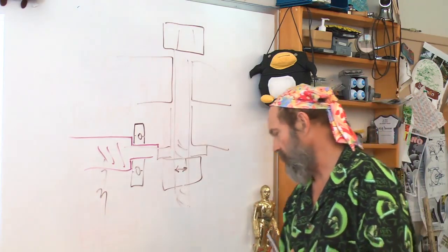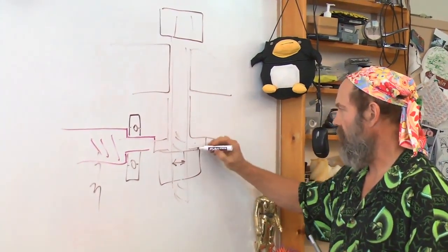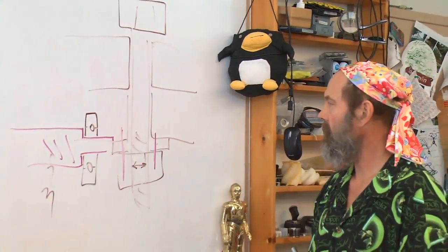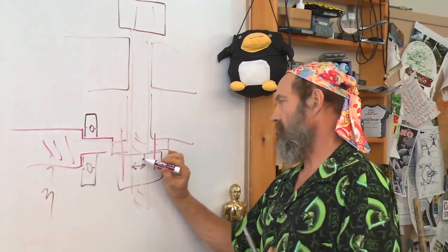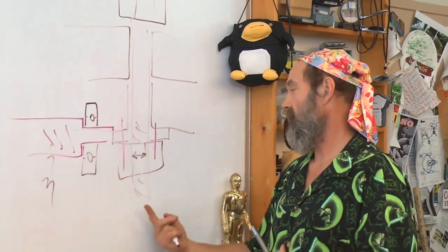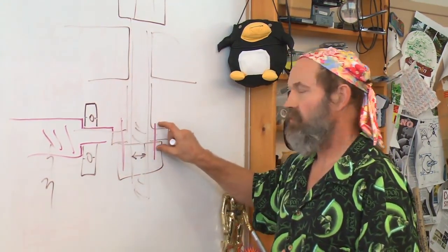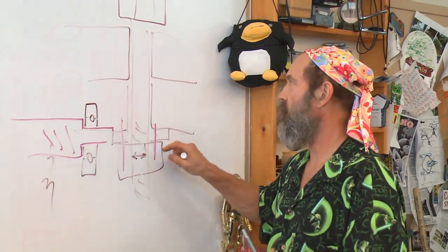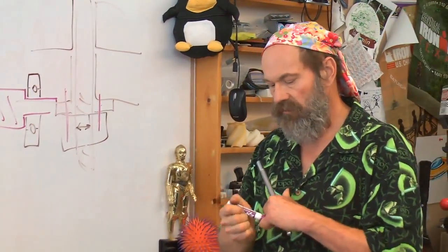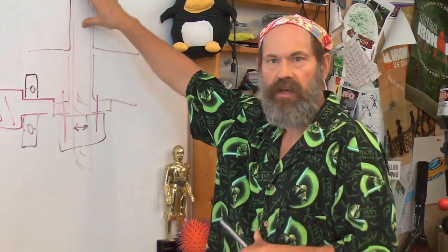The frictional loss between the nut, the washer, and the part happens at a much bigger diameter, typically almost 1.5 to 2 times the diameter. So if you think that the frictional losses in a screw system are high when you have just a regular plain nut and bolt, they're even higher typically between the nut and the washer interface, which is why it's very important when you're using bolts where you want to get a prescribed force to preload elements together, for example, in doing a structural joint, that they be properly cleaned and lubricated as the torque is applied.